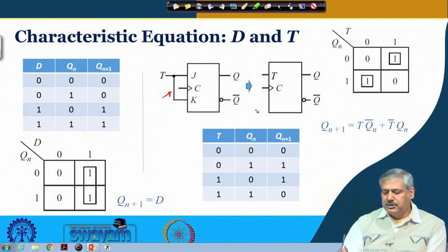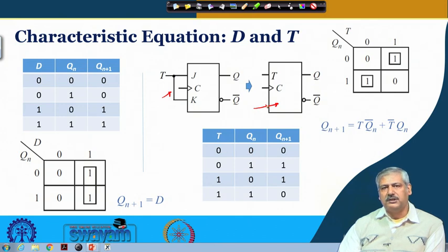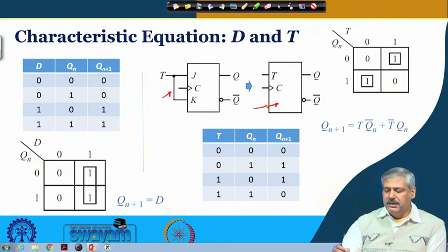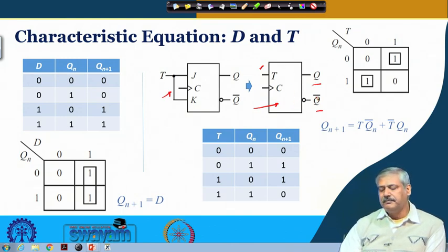All those things are pushed inside the logic circuit within a particular group where all the elements are there, and then what we get is a single input flip-flop. Of course, it is clocked, positive triggered and all, and the Q and Q bar are outside, that is why this bubble is there. If they are inside, the convention is not to put the bubble. I mean, for the symbols Q and Q bar, if they come inside, a bubble is not put. We have discussed this before. So, this is your T flip-flop.